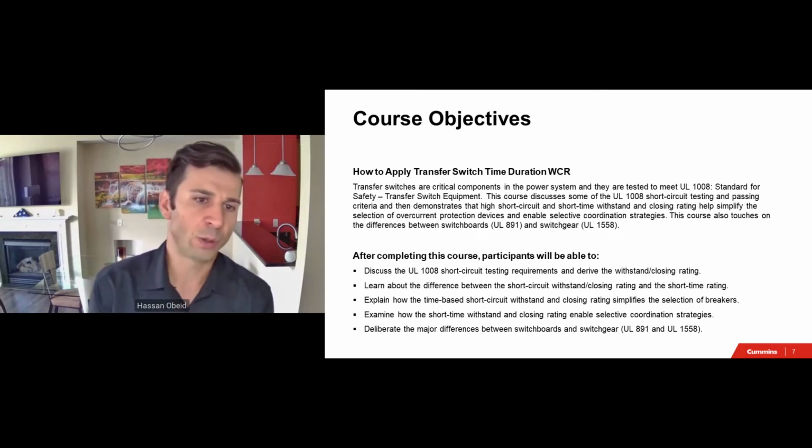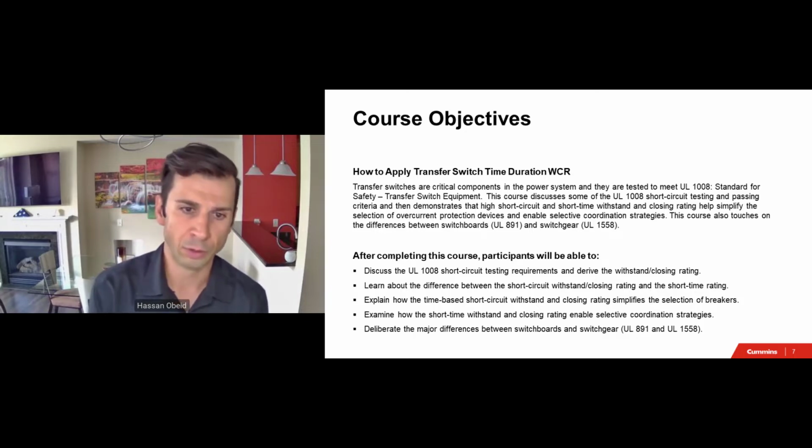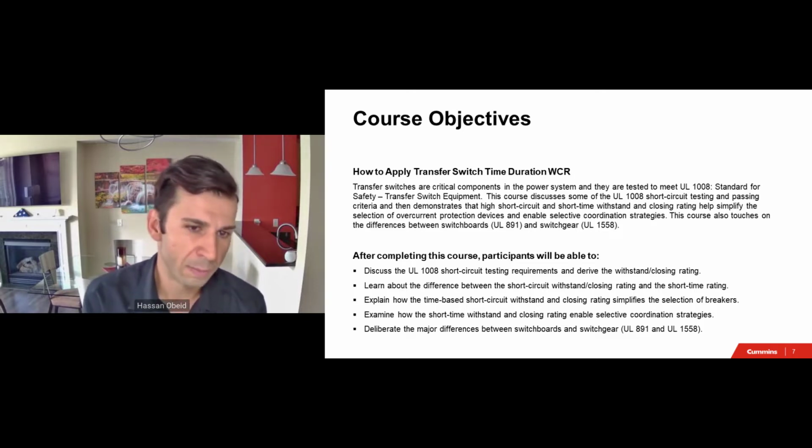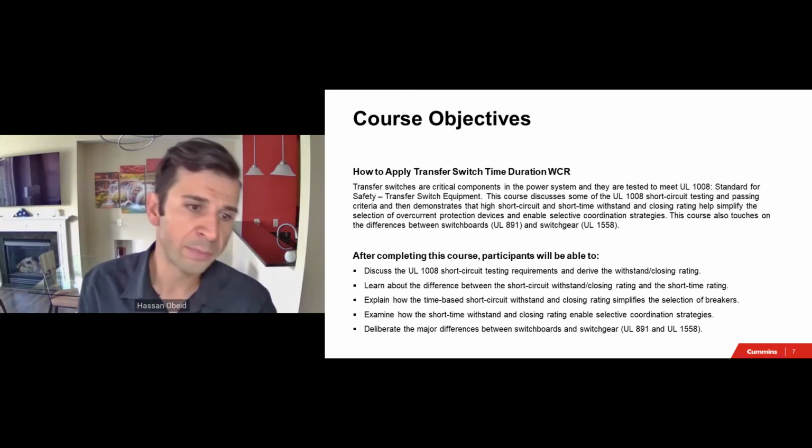So after completing this course, you will be able to discuss the UL 1008 short circuit testing requirements and derive the withstand and closing rating. Learn about the differences between the short circuit withstand and closing ratings and the short time rating. And I'll give you a quick hint: the short time rating is also a short circuit test.